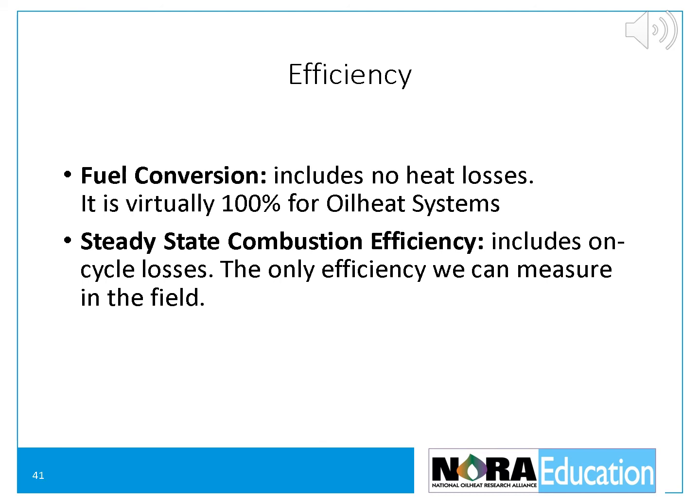There are still many old, oversized boilers with 1970s flame retention burners. What we used to do in the 70s was, with careful nozzle sizing and adjustment, the CO2 on these units can be as high as 10%. Lowering the firing rate by putting a tiny fire in that big pile of cast iron can probably get the stack temperatures down to about 400 degrees. This works out to 81.5% combustion efficiency.